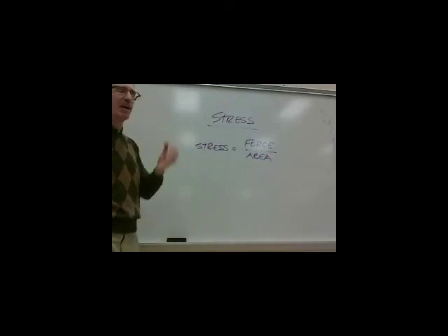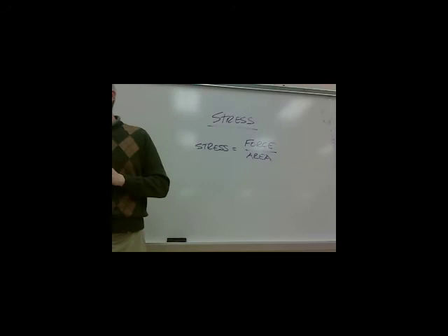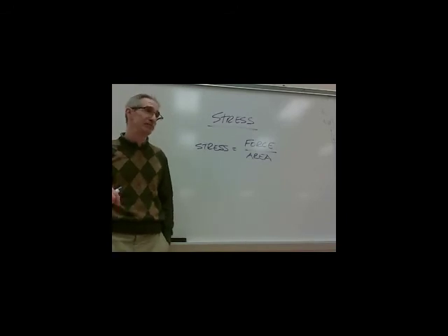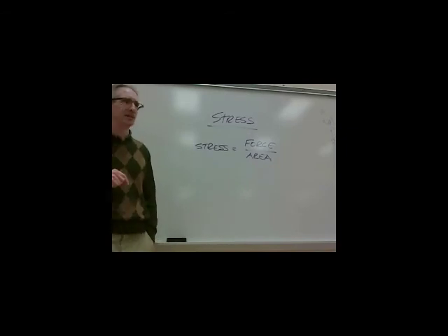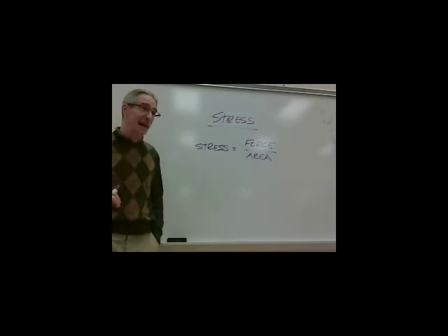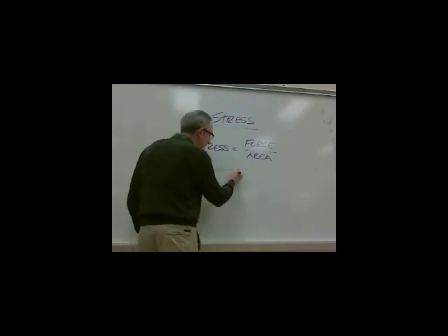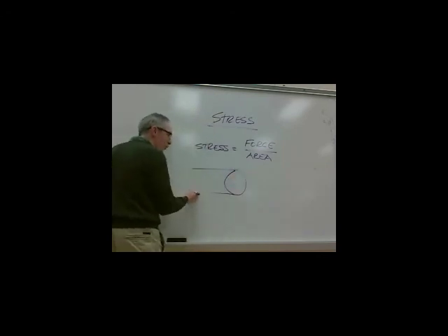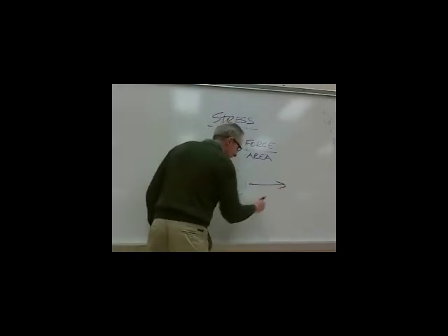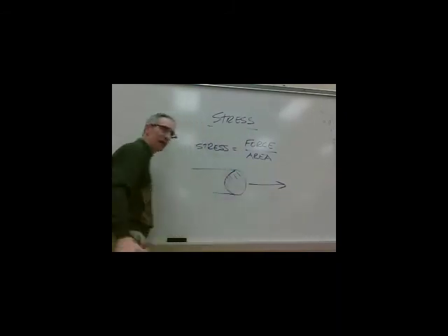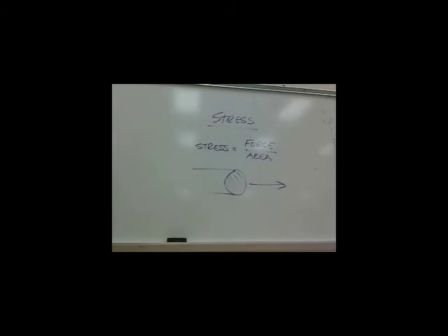Okay? Now, the area that we're talking about here is what I would refer to as the area that's resisting the force. Okay? So always ask yourself when you're in a problem and maybe you're asked to determine what the stress is in the member, think about the area that's going to be resisting that force. Now again, if we're talking about the rope in tug of war, I think you'd have to tell me that that force is being resisted by the cross-sectional area of that member, right?